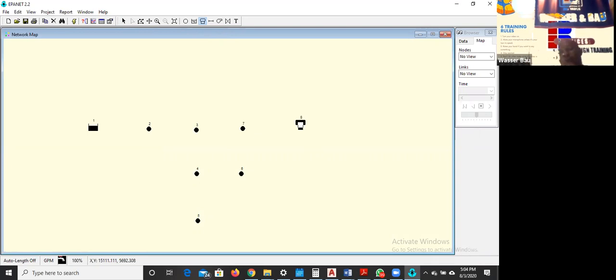That becomes my tank. Now, if any of the nodes is not in order, what you just need to do is go and click on this select tool again. Then click on the node. Then hold your mouse down and drag it. I know some of us don't have a mouse, but anyhow you know how to hold and drag. If I want to move this tank now, I'll click on the tank, it will highlight. I can hold it down and then drag it.